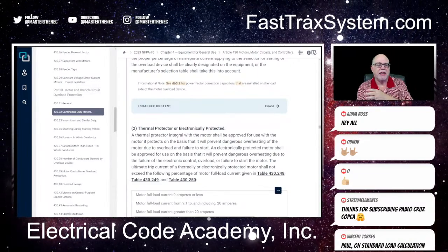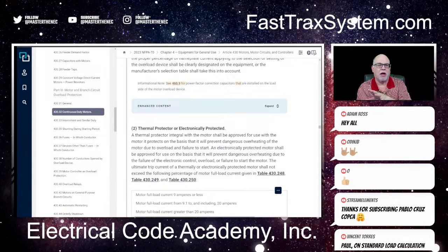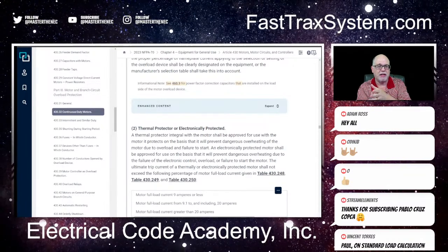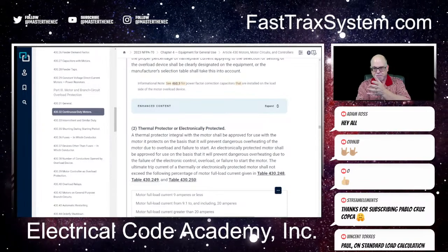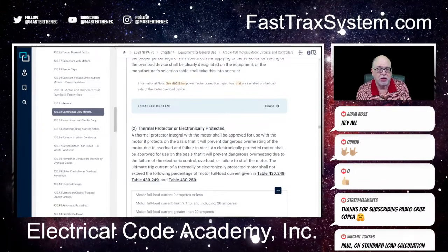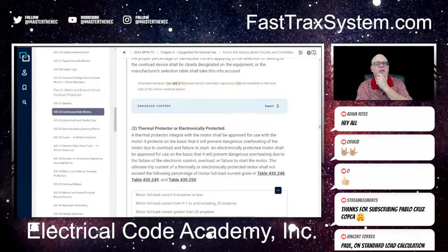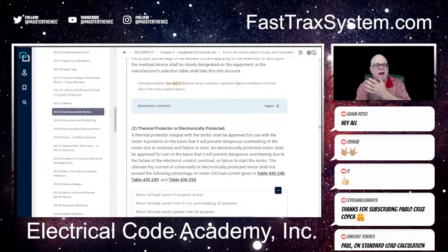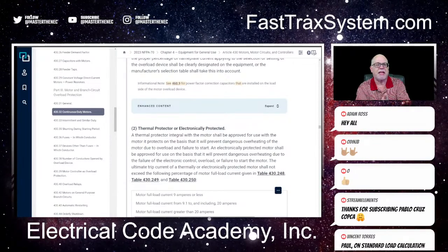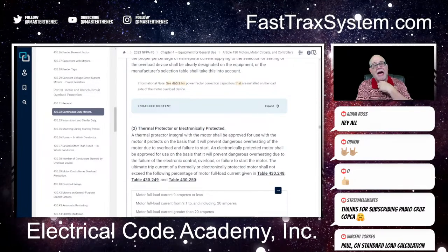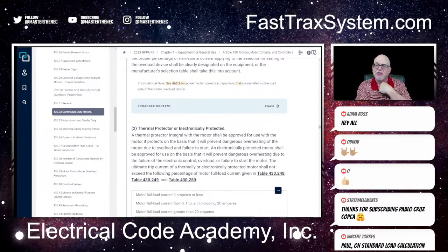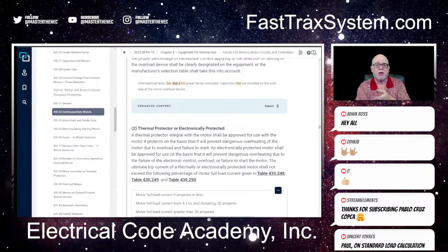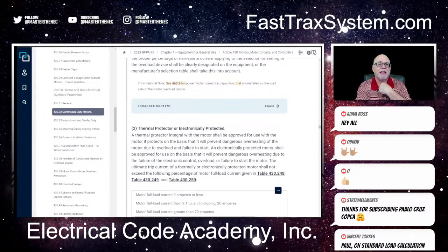So here's the interesting thing. Cooking is not a requirement, believe it or not. Cooking appliances are not a requirement in a calculation. Same as a dryer is not required. However, if somebody puts in an electric range plug, a 50 amp or whatnot, how I would account for that is I consider that permanent provisions for it, or it's installed. I'm just giving you my opinion on it. If it's there, that means somebody could plug into it.